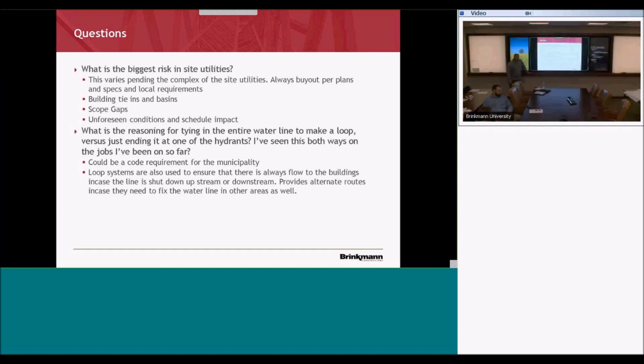Does that include just the system itself, or does that include the dirt on top of it? Again, typically that unit cost would be just that system. For underground large box detention, it's usually just the detention box, because most of those, if it's a big box, are dug by the excavator. So that's a different unit cost, and then backfilled separately, because that's a different unit cost.